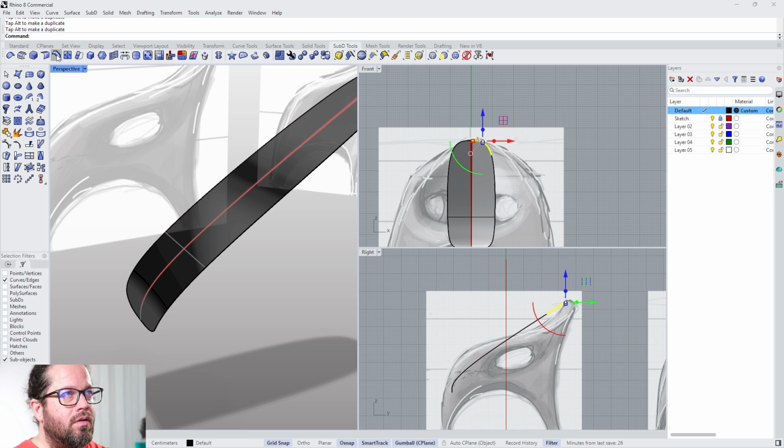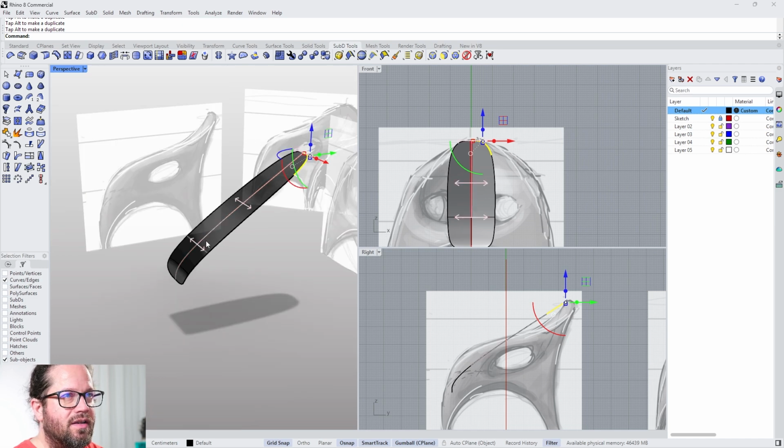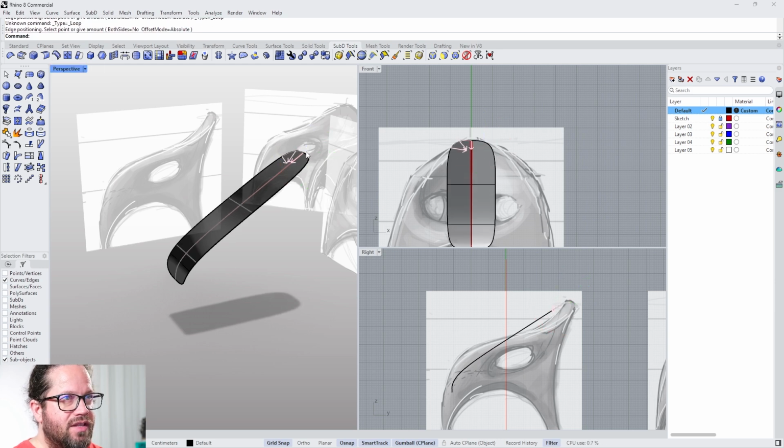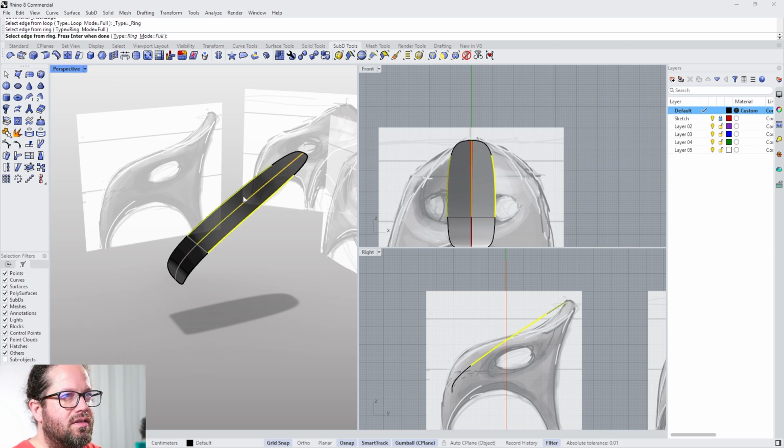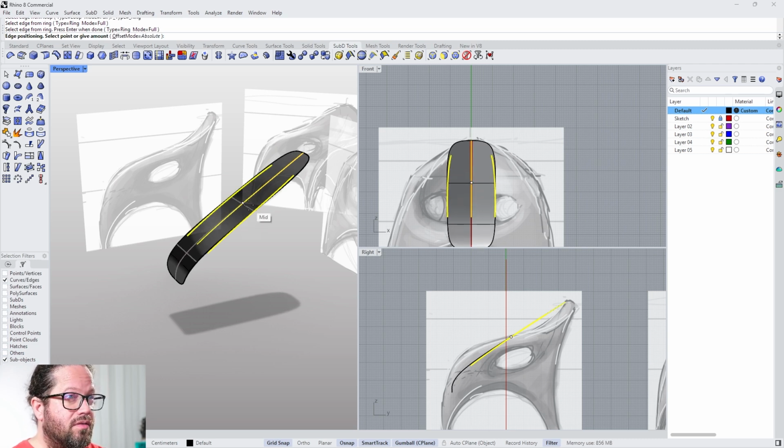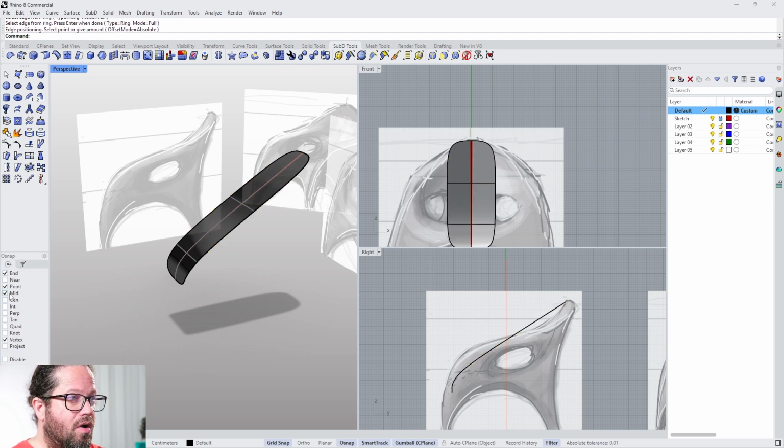And we can now create an edge loop. It's basically a subdivision of this. We divide this long face into two, and we can do that by either clicking directly on it with left mouse click. For that you need to have this edge here selected, or what I kind of prefer, because this is how I learned it a bit from Blender, it is more similar to the Blender method, but it's up to you. You can right click here and then select the edge perpendicular to the edge you want to create, right? And then you can set it into the middle. It snaps to the middle because we have mid on here in the snapping.